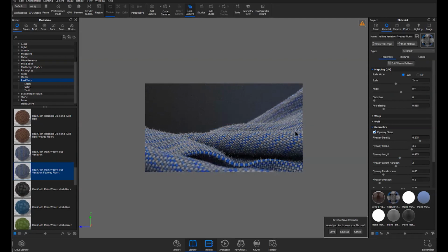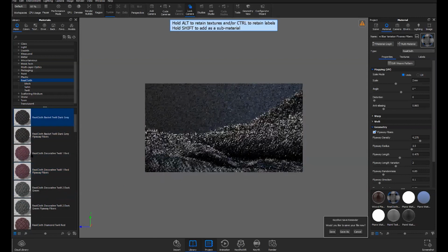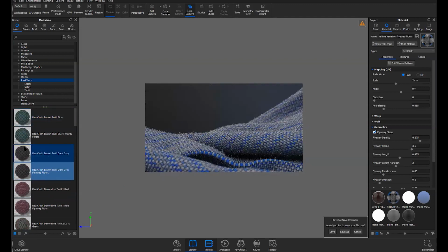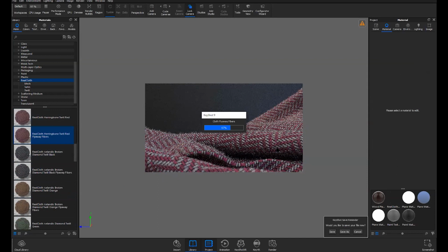Go ahead. I was saying, because it's actually a procedural mesh, there's space in it, the light's not reflecting on it like it's a hard surface, the way you would with a flat material. So you want to make sure that if it is white, you have directional light on that versus soaking it in from outside.